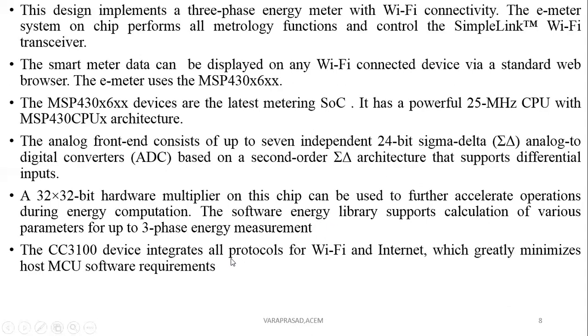Okay, then CC3100 is also available within this chip, which consists of all protocols for Wi-Fi and internet, which greatly minimizes host microcontroller unit software requirements, because this CC3100 consists of all the software which is required for interfacing to any microcontroller.